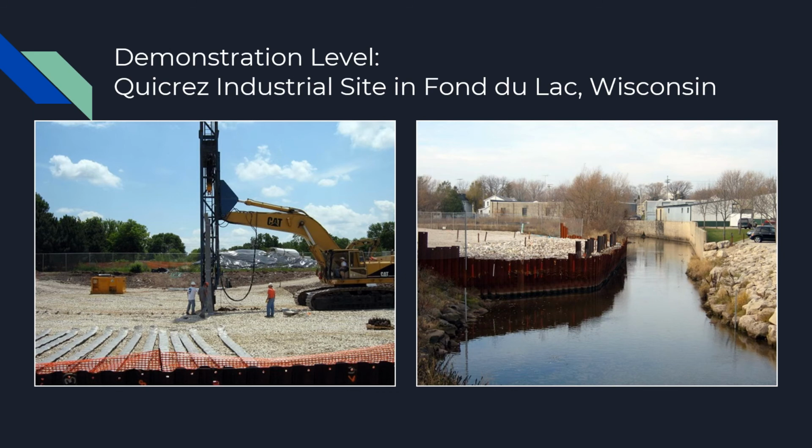The economic conditions of the state by then started deteriorating, and hence the funding for this site was eliminated in 2009. Results. After the funding was stopped, the post-treatment sampling showed significantly lesser DNAPL concentrations. If the treatment had continued for some more time, it would have been possible to reach the target contaminant levels. More than 2/3 of the total TCE was removed, and the zones of DNAPL diminished. The iron filings were still existing and continue to contain any TCE that might migrate across by diffusion or convection for years to come.